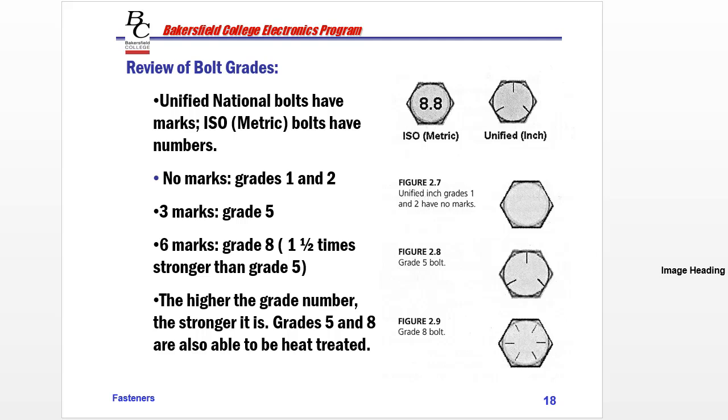So let's say, for example, you have a machine at work, and every so often, maybe about every 6 weeks, you have a bolt that breaks. If you have been maintaining this machine from brand new, you definitely need to look at the root cause of why the bolt keeps breaking. Now, if you haven't maintained this machine from brand new, how do you know that the bolt you have removed that is broken is actually the correct bolt to be in that machine?